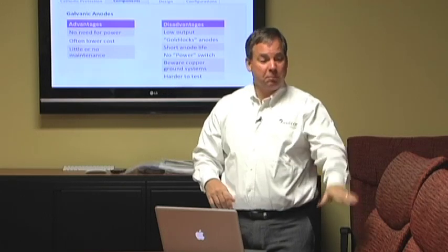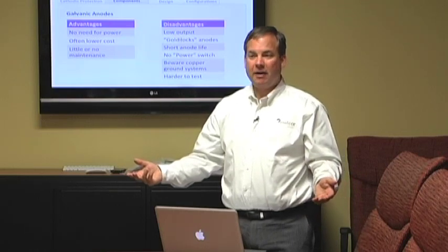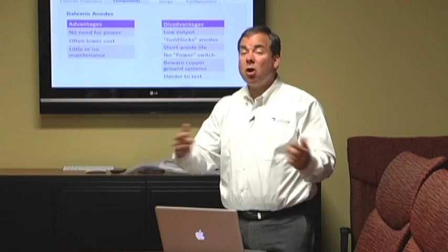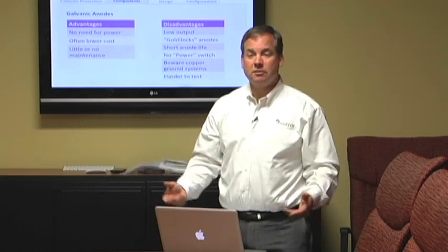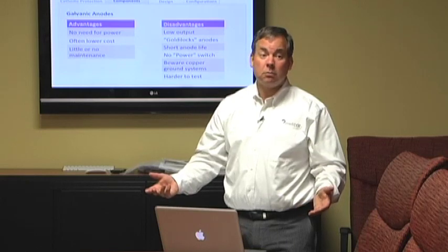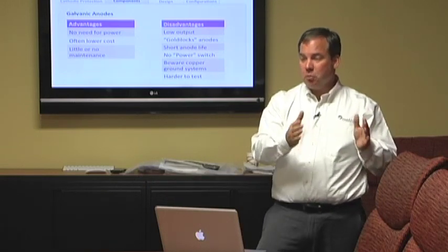The galvanic anode system is buried, the pipeline is buried, it's forgotten about 5 years later and nobody's testing. In fact, I got a call yesterday from a guy. He's got a pipeline protected with galvanic anodes. I asked him, have you had it tested? He says, no. Do you know it's working? No. Now, if he had a rectifier and a power supply, he could look at the power supply and say, yep, it's still working.